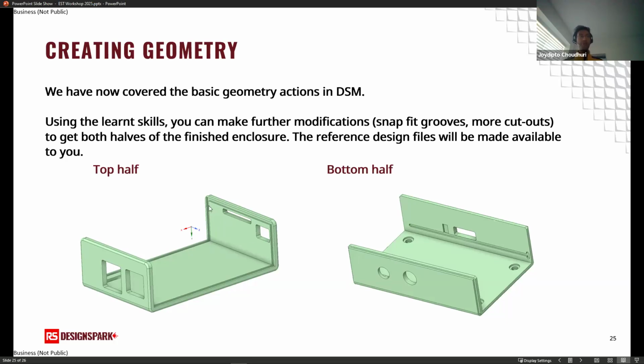You can just, again, like I showed you, go into sketch mode, construct your profile here, and then use the pull tool to drag through and create the groove here. I will also share the files with you so you can have reference as you practice on these designs. So there's your two halves. These two snap together, and in the middle sits your Raspberry Pi board.